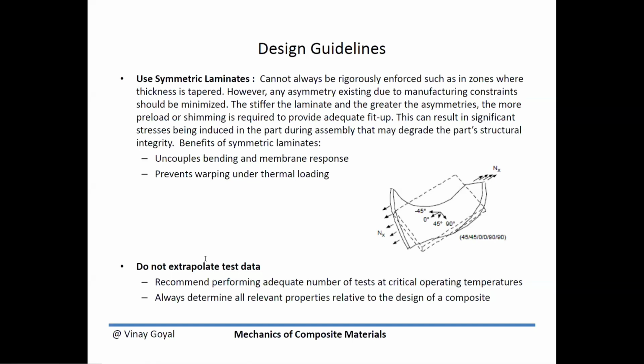And so the benefit of using symmetric laminate is that you're able to prevent warping under thermal conditions and also uncouple the bending and membrane responses. We talked about some of this before, just trying to bring that to light again.